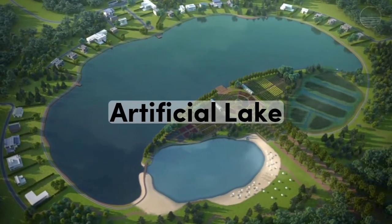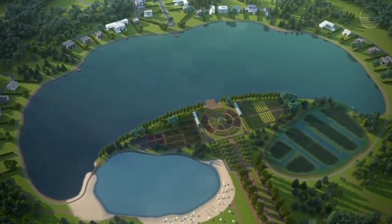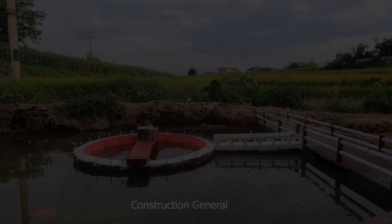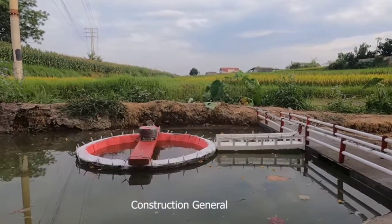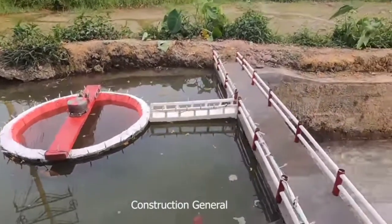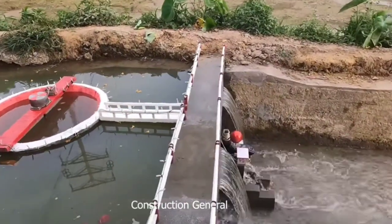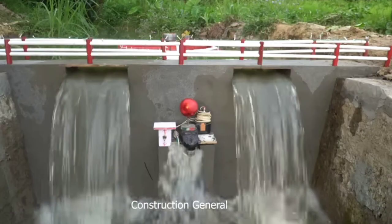So next, the artificial lakes. Artificial lakes are man-made water bodies that offer a possible alternative. The heat effluent may be discharged into the lake at one end, and the water may be withdrawn from the other end for cooling purposes. The heat is eventually dissipated through evaporation. However, these lakes have to be rejuvenated continuously.